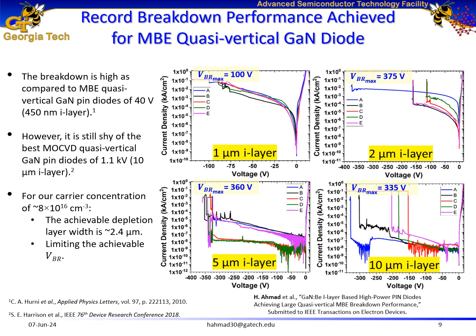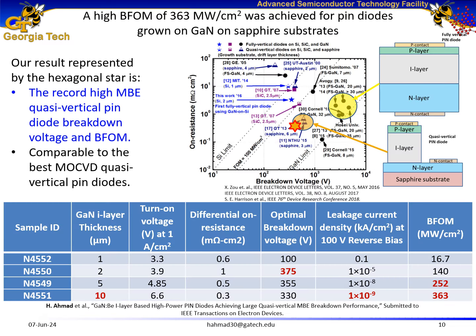One significant point that we see from comparison of the thicker devices versus the thinner devices is that the thicker devices show leakage current which is significantly lower, approximately 7 orders of magnitude lower as compared to the thinner devices. So we used a doping of 1 x 10^17 per centimeter cube and achieved a carrier concentration of 8 x 10^16 per centimeter cube.